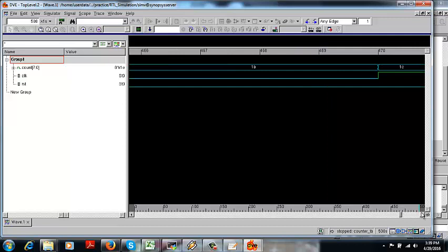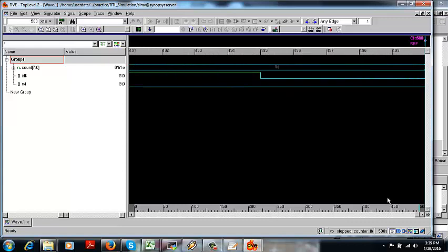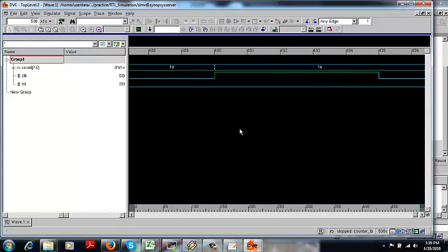So now you can see the difference. So it's exactly happening, right? I'm getting an output exactly at the rising edge of the clock. So the timing information is not at all there in your functional simulation, which you are able to observe in a gate level simulation.